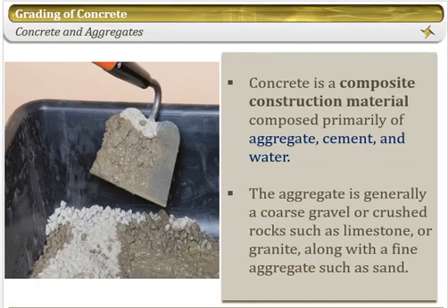So, coarse aggregate includes gravel and crushed rocks, such as limestone and granite. These crushed rock particles are also known as coarse aggregate. Actually, the size of the coarse aggregate is more than 4.75 mm when we do the sieve analysis, and 2 mm to 4.75 mm aggregates are also known as sand. Locally, we know the coarse aggregate as gitti or rodis, and fine aggregate is locally known as bajri.